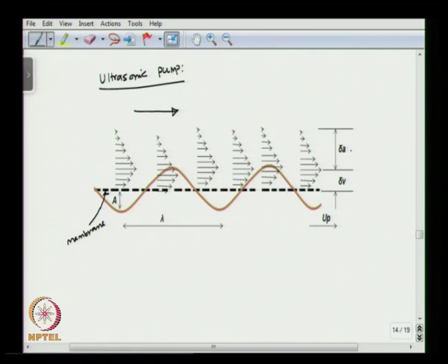and so there are two parameters to define here, one is the acoustic evanescent length and the other one is the viscous evanescent length. The viscous evanescent length is the distance in the y direction from the surface of the membrane to a point where the velocity is maximum, okay. And the acoustic evanescent length is the distance between the point where the velocity is maximum to the point where the velocity in the bulk reduces to 0, okay. So, there are two important parameters here.